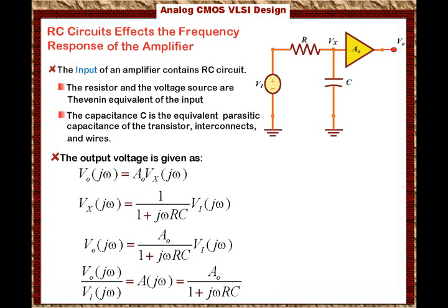And that signal Vx is a function of frequency, then Vout will also be a function of frequency. Now keep in mind that the actual amplifier inside the IC chip contains the capacitor and the ideal amplifier, because the capacitance is parasitic. Remember that inside the IC circuit, we're going to find an equivalent capacitance at the input. We will show you in this lecture how to evaluate the input equivalent capacitance.